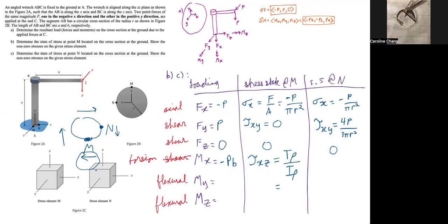So since the shear stress over here has to be pointing to the left, it will be negative. So we add a negative sign here, negative Pb. And just note that if you add a negative sign over here already, we're taking the torque to be an absolute value. So we'll take the absolute value of negative Pb.